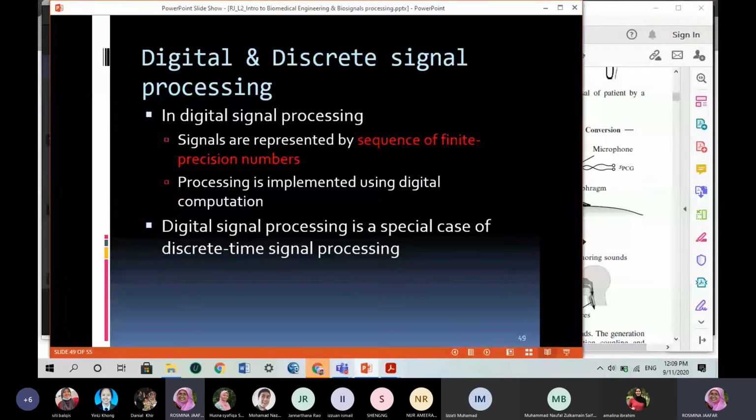because you do the processing only on finite values at finite times. In between the time samples, you don't have the data, so you don't know what's happening. So if your sampling time is too slow, for example, if you sample every 1 second, which is 1000 milliseconds, maybe within that second, at around 100 milliseconds, something has changed.